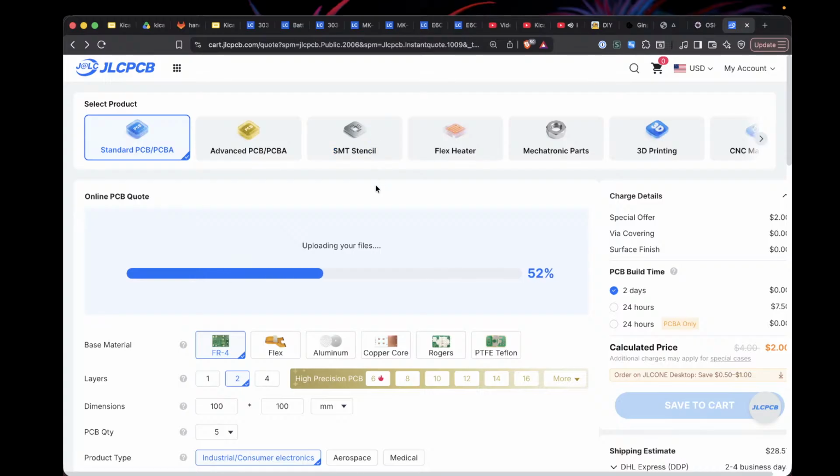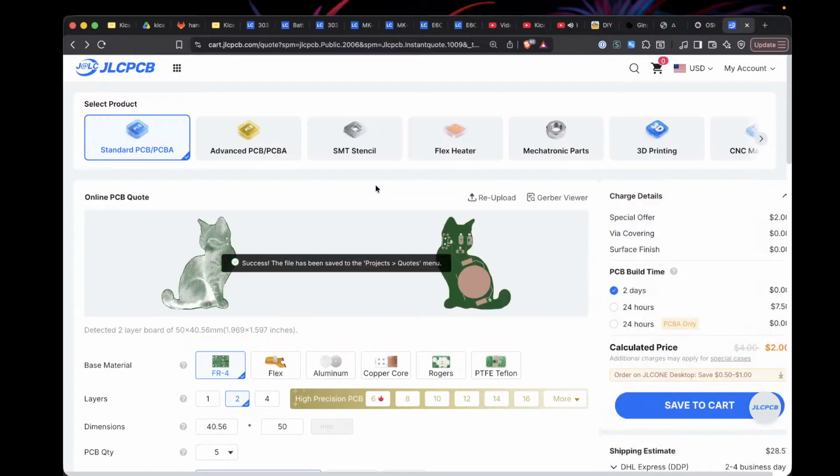This one's so simple, you can hand solder it, but if it's more complex, you'll get a stencil for it. So you'll almost like silk screen squeegee the solder paste onto there. And then you place the parts, put it on a hot plate or put it in an oven, and it's real satisfying when you get to that point.